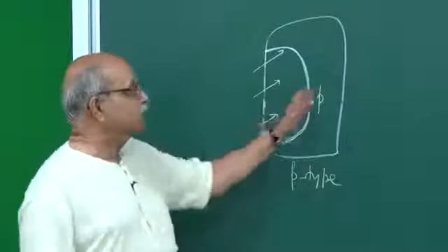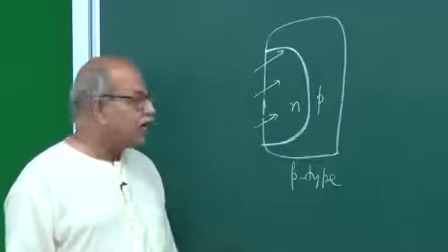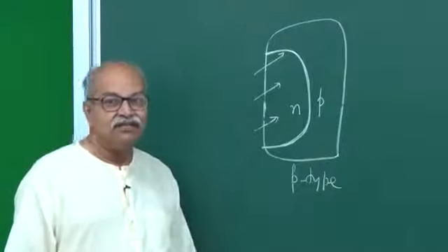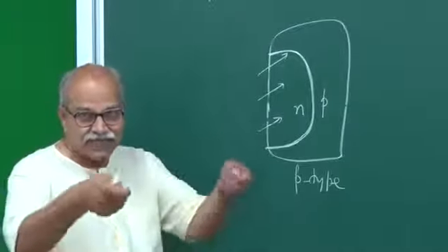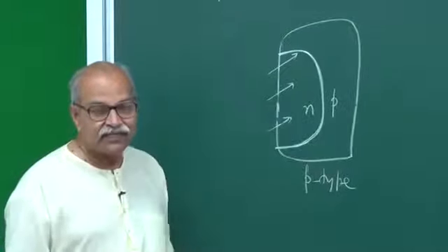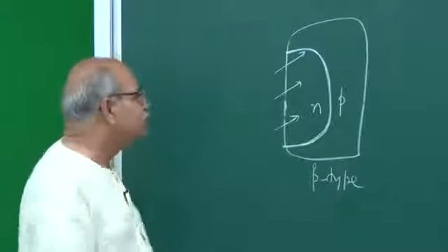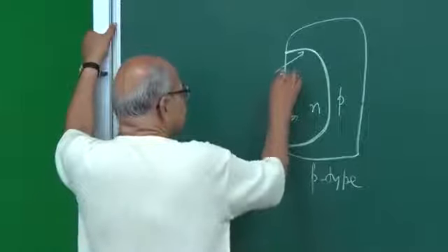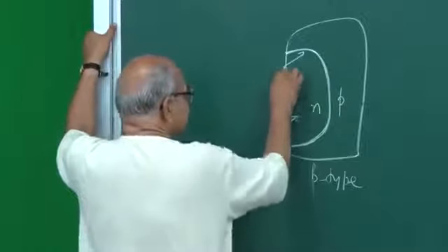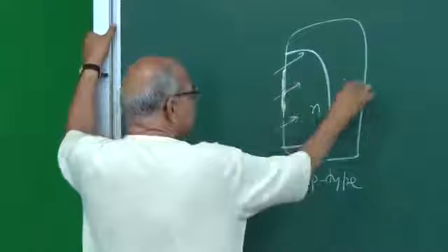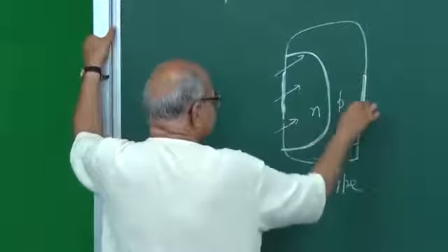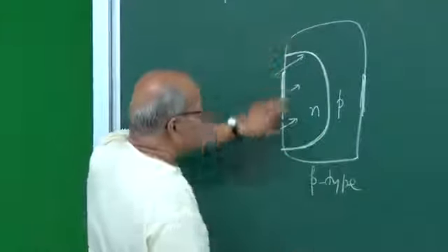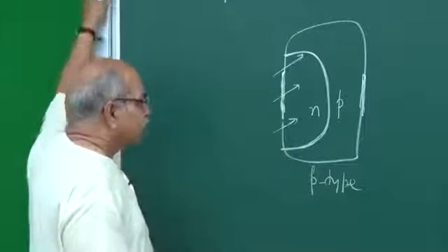So, this is p-n junction, and if you want to use it for external world, you should have metallic contacts from where you can connect wires and put this into circuits. So, in a very controlled fashion, once again, aluminum or some metal is deposited either on the back side or on the front side itself. You can have a p here and metallic contacts.